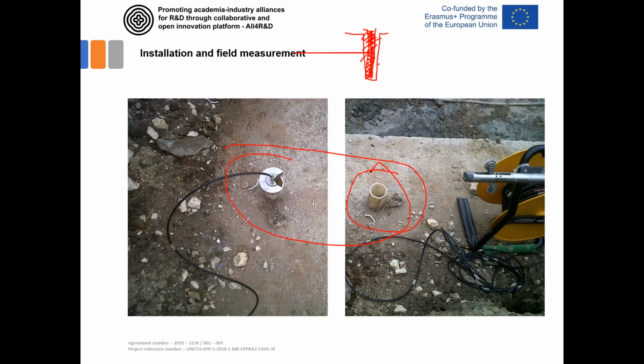After that, we can perform the initial measurement to define its initial position. The initial position does not have to be absolutely vertical, but never mind. We have some initial line. Any additional change of the slope of this line will define the horizontal displacement, and not only the displacement, but more importantly, the depth of the sliding.